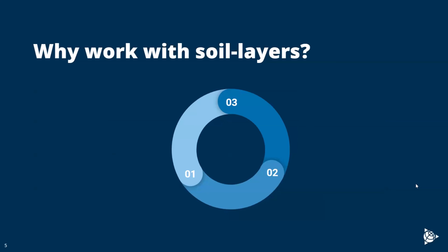So why should we work with soil layers? You could ask, isn't it enough to just use the ground surface? And yes, you do get results using the ground surface, but you won't get the correct volumes, especially when working with modules in Novapoint. So that's the first reason.